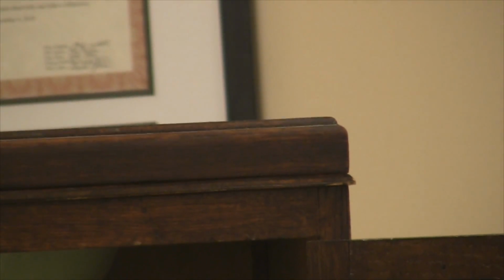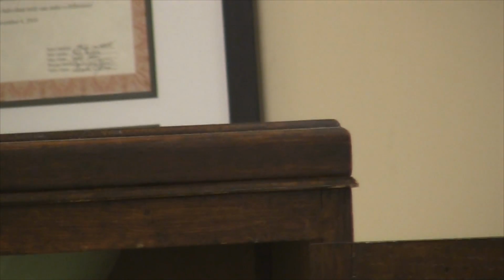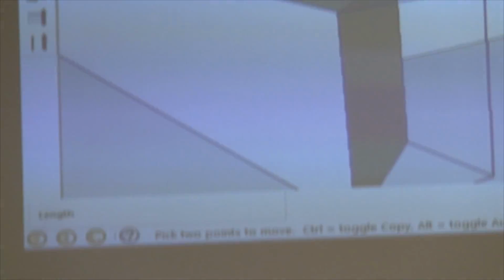So from here, I'm going to orient this to that surface. I'm going to start flush, but I'm actually going to drop this down and give this a 1/8 inch reveal. And so that will allow me to have that surface like we see on this piece here. So you see that little lip right there. On my original one, I think I actually made that a 1/4. I'm going to drop that down a little bit. So now again, we have this as a component.